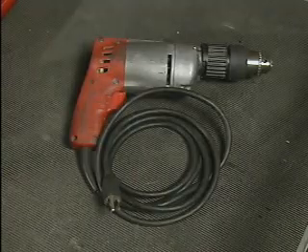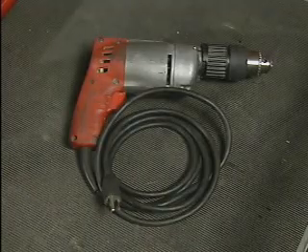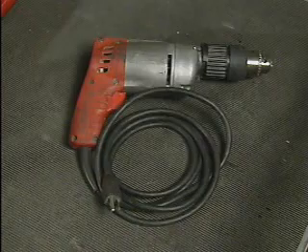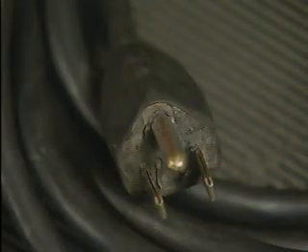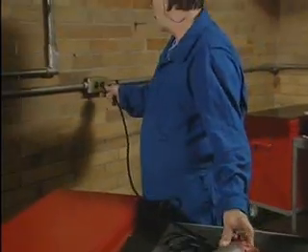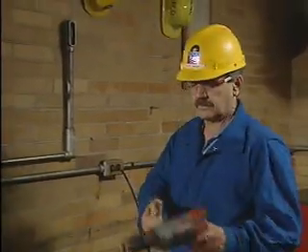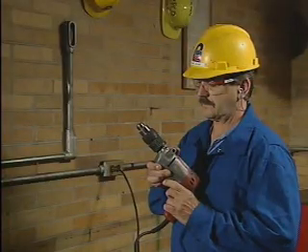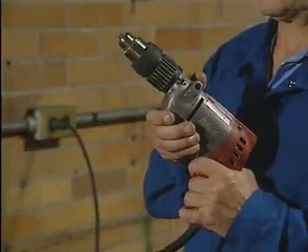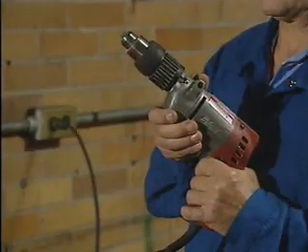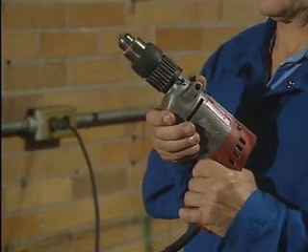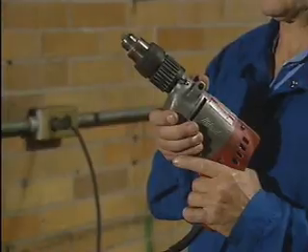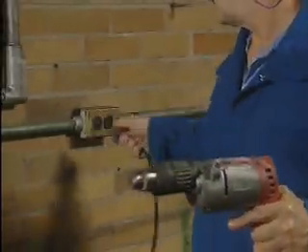Like equipment that's installed in your facility, proper grounding is also required for many portable tools that you may need to use. Any tool that has a metal casing should be equipped with a grounded three-pronged plug. When the tool is plugged into the proper type of receptacle, the third prong connects the tool's casing to the equipment grounding terminal in the power receptacle. This means that fault current will travel from the tool's casing to ground through the ground conductor in the power cord, not through the body of the person using the tool.